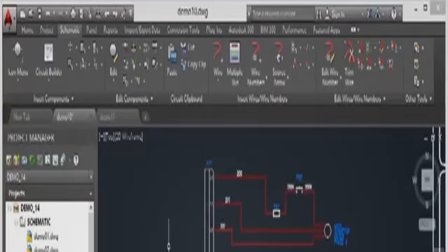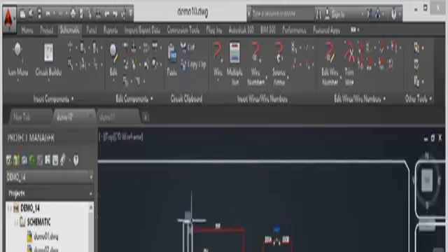Now can you see we've got question marks again? If I zoom out on the drawing here, you'll notice that we don't actually have any reference markings, such as an X zone or an XY grid anywhere. That's why those are going to question marks in this particular case, because I've moved it from a known location and it doesn't find any reference markings to use, hence the question marks.